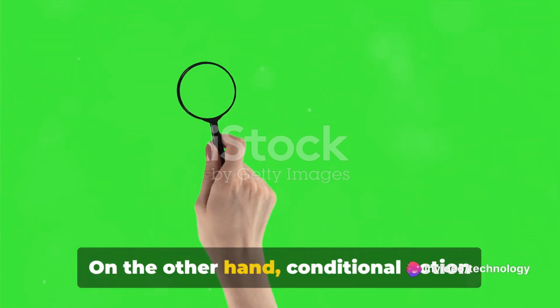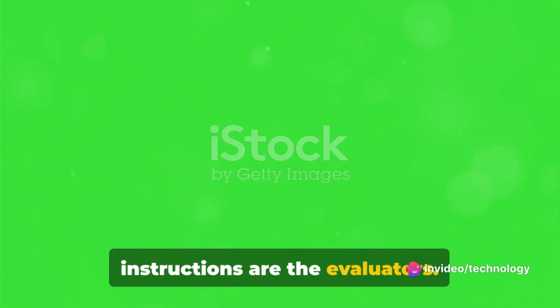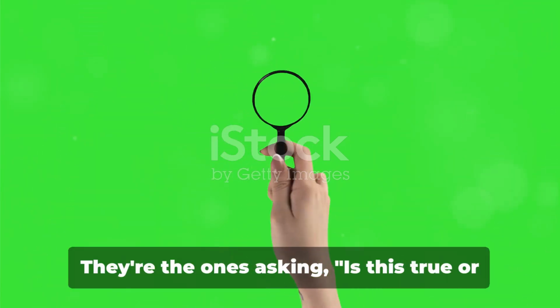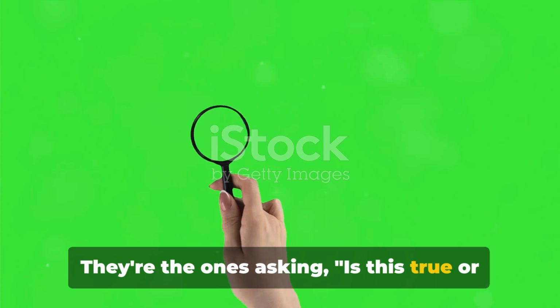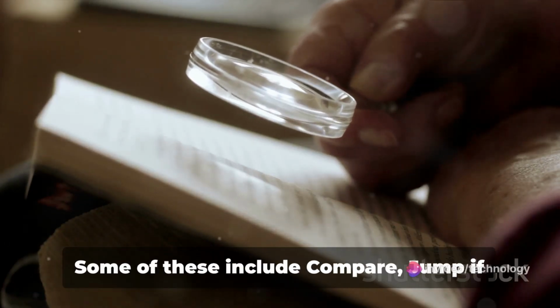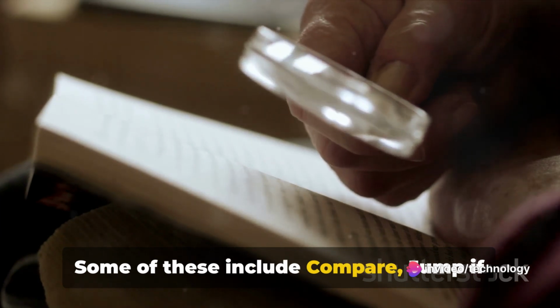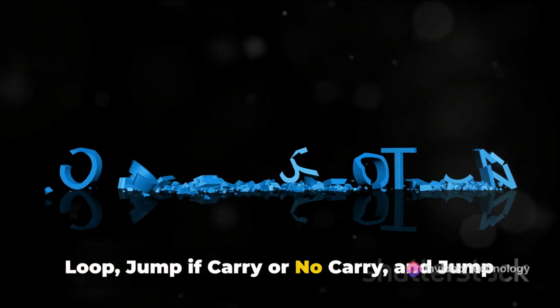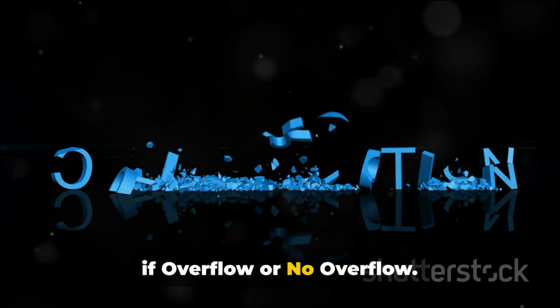On the other hand, conditional action instructions are the evaluators. They compare, assess, and jump based on the results. They're the ones asking, is this true or false? Is this greater or less? And then deciding what to do next. Some of these include compare, jump if above or below, jump if greater or less, loop, jump if carry or no carry, and jump if overflow or no overflow.